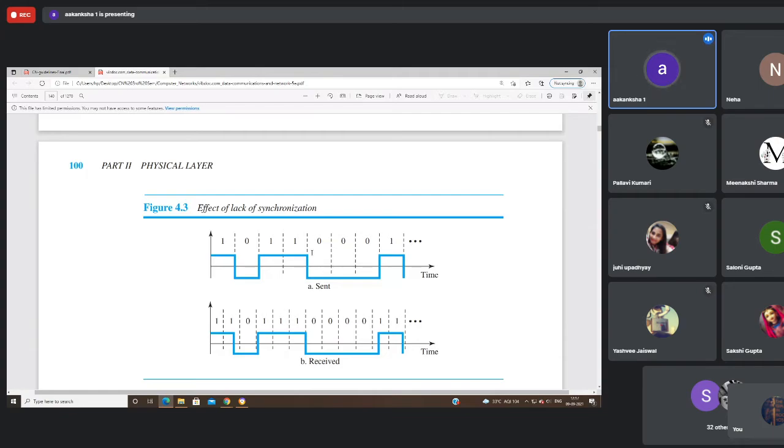Similarly here, it is sending continuously low negative voltage for zeros for this entire duration of 3 clock cycles of the sender. But during this time, when the sender has counted 3 clock cycles, the receiver has counted more than 4 cycles. So they are interpreted as 4 zeros. Similarly, in the middle of this last second clock, it has changed the voltage level, and now it will be represented as 1 and 1.